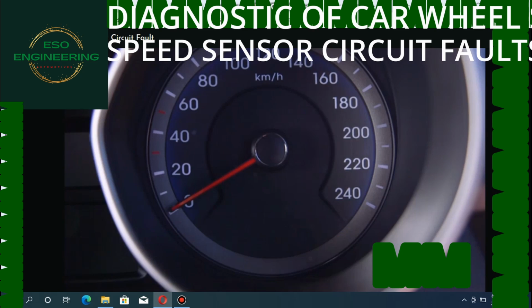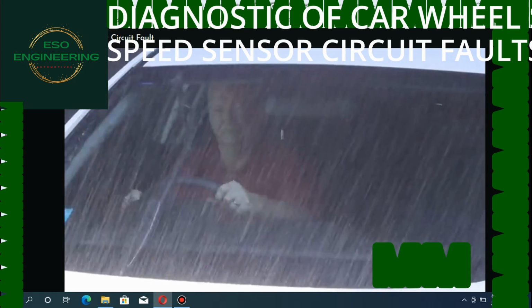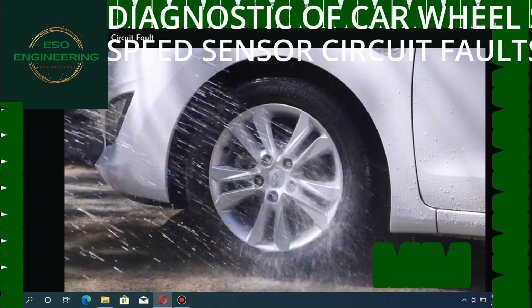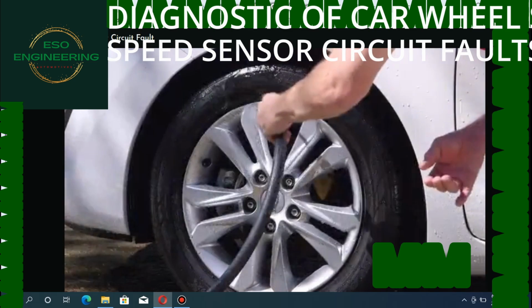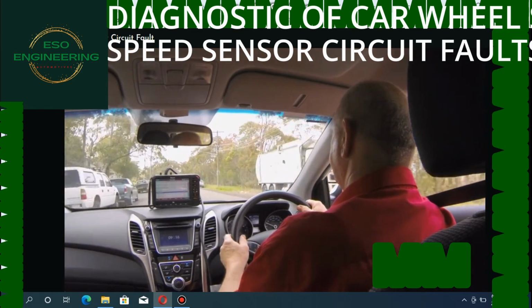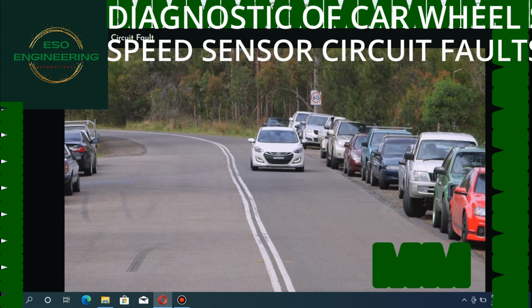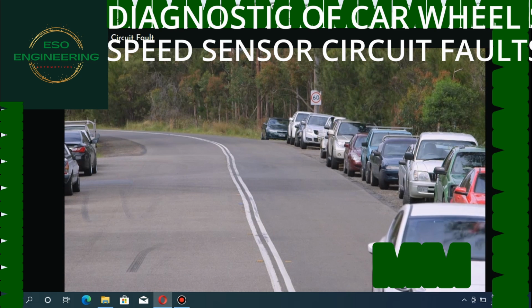If the customer comments that the ABS indicator is on only during moist environmental conditions, such as rain, snow, vehicle wash, etc., inspect the wheel speed sensor wiring for signs of water intrusion. If the DTC is not current, clear all the DTCs and simulate the effects of water intrusion. Observe the scan tool wheel speed sensor parameters while driving in a straight line at greater than 40 kilometers an hour or 25 miles an hour. The readings should be the same on all sensors.